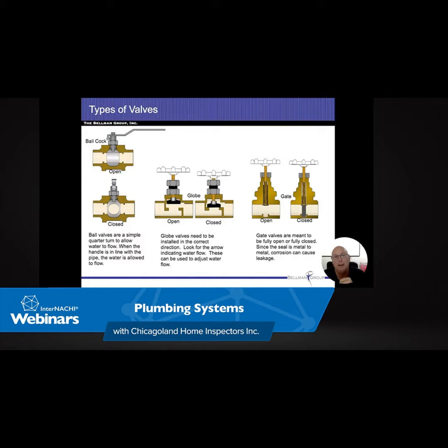Double traps, we did see this on one of the houses that we did a field training on, I don't know, about 3 or 4 weeks ago before making this video. They actually had the shower trapped, and then the shower went into the drain for the sink, which was actually trapped in the basement and not under the sink above.